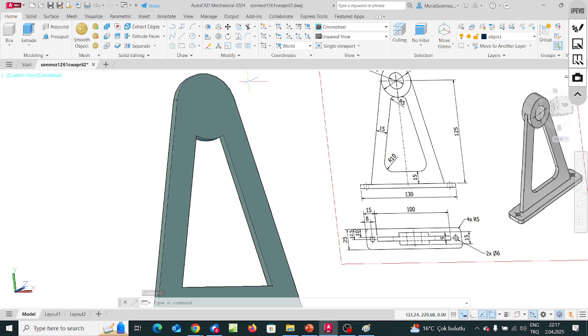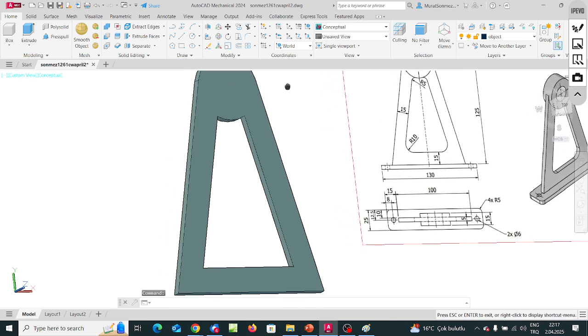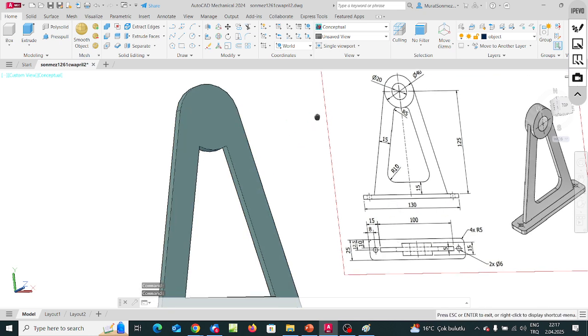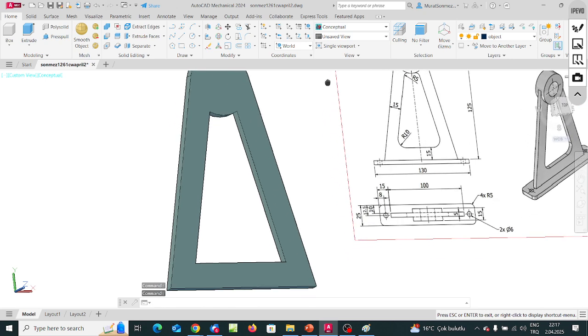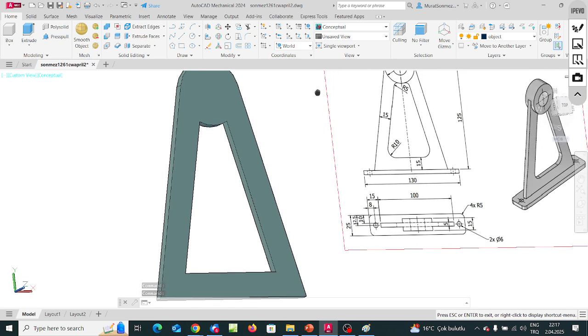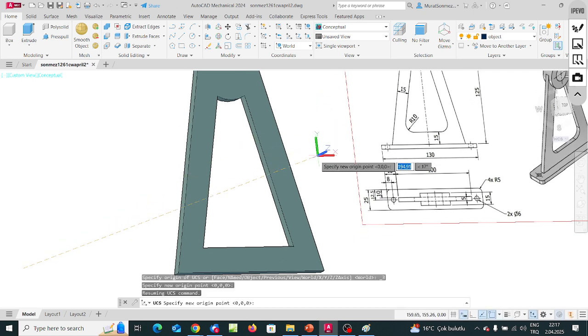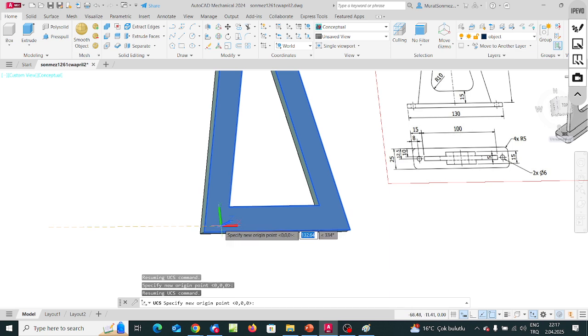Okay, to be able to create a circle here, to extrude the cylindrical extensions, I think do it. Locate the XY plane as coincided with this surface. Okay, while this surface is being highlighted,